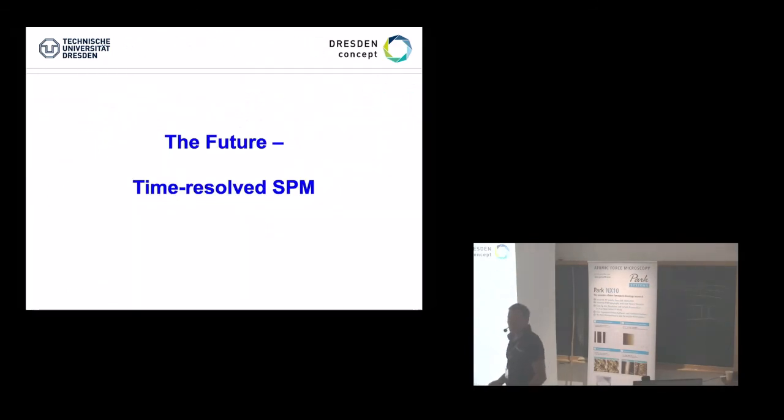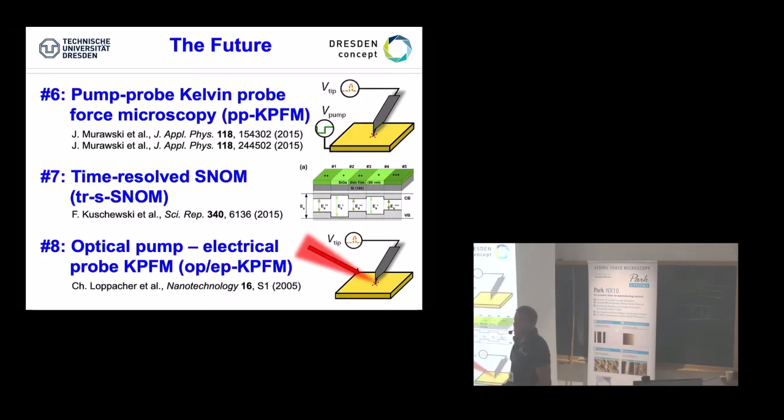one last slide, because all these scanning probes, and that was really the beginning question, can now also go into very high time resolutions. We can go, for instance, by adding more resolution in time to our Kelvin. So the mode that I showed you before does not necessarily mean we need to measure DC or CV. That means my voltage source here can also be a pulsed source, right? So what happens then? We have a completely different time structure. We build up something, and then we can measure later. And that's exactly what you see here.